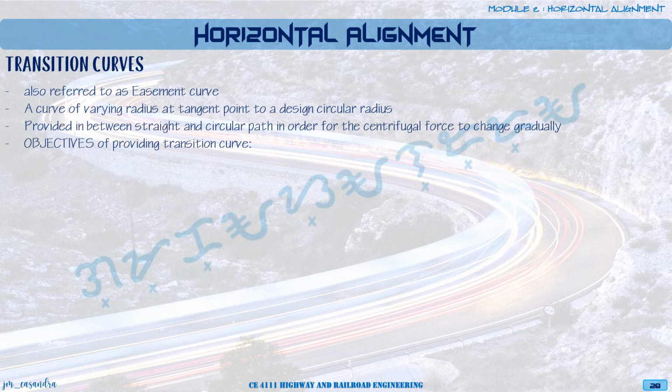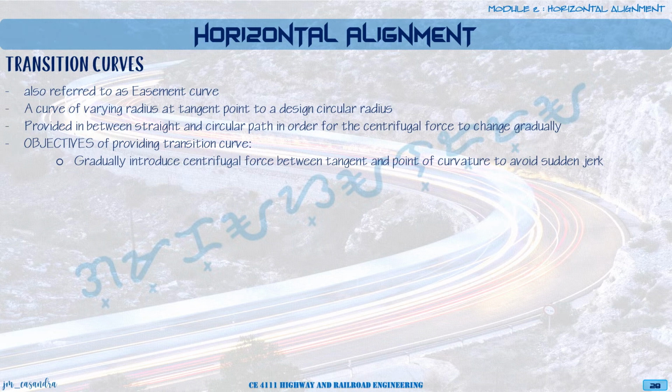So the objectives of providing transition curves would be the gradual introduction of centrifugal force between tangents and point of curvature so as to avoid sudden jerk or sudden change in acceleration. So also, by providing transition curves, we are increasing the comfort of both passengers and drivers.